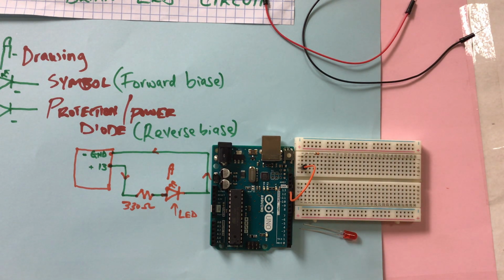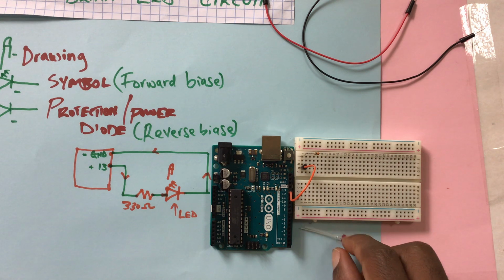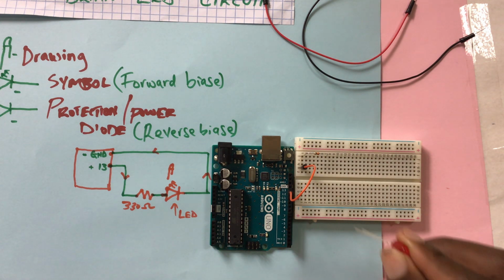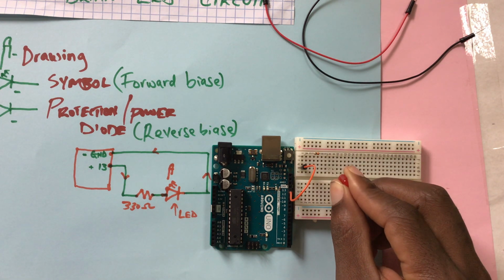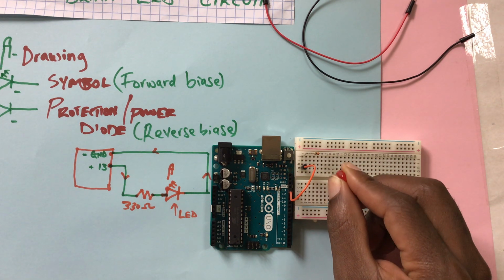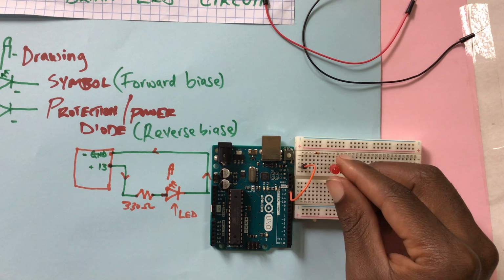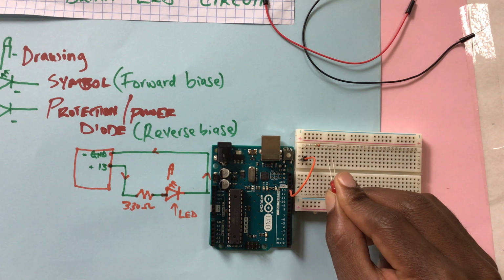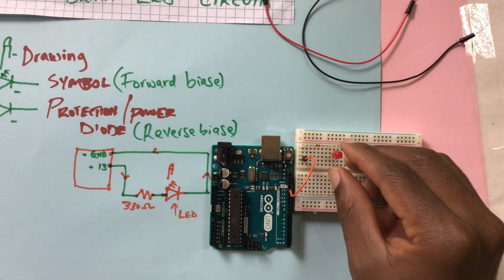After putting it to number 1 and 7, the next part we want to connect is this. The long side of the LED, we want to put it to this line connecting internally to the resistor, which is number 7. So the long side is going to number 7, which is the positive side, and the short side we will put at number 8. Anything along this line will be okay. So we just do 7. Make sure you see the long side. Long side is going to 7. Short side is going to 8.